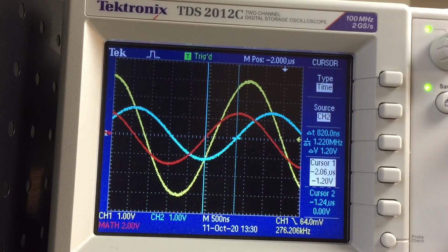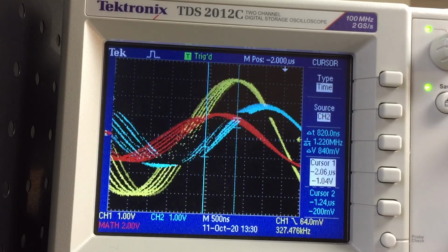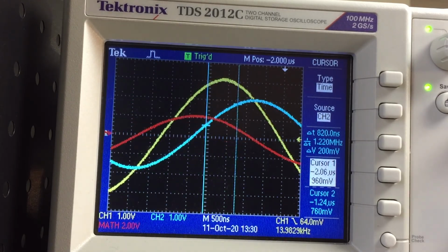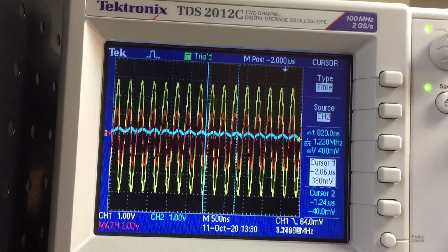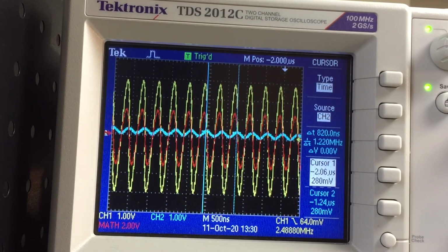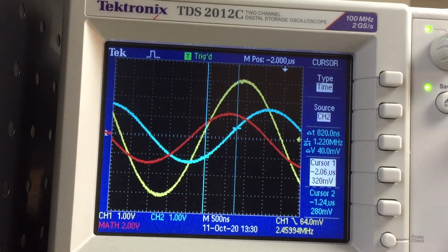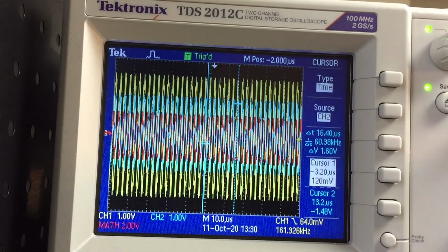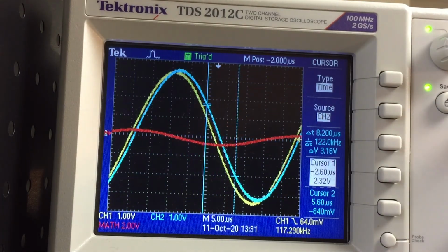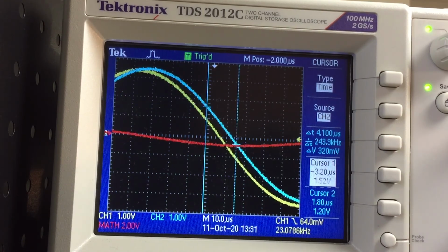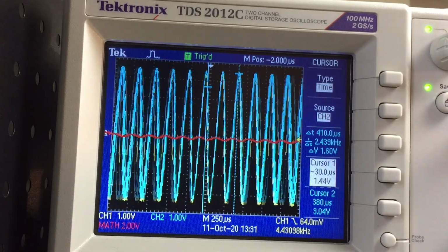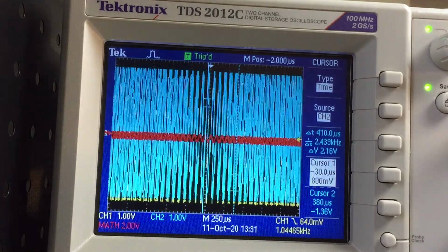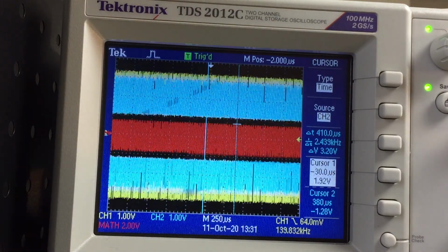Now the impedance of a capacitor should decrease with increasing frequency, so we should get more current. And let's crank it up a bit. We're pushing the limits of this breadboard, but let's do it. Indeed we do get more current. Let's crank it down now the other way. And we're going to have to scale out on our oscilloscope here. Where's that red trace? And we're going to crank down the frequency, and indeed we get a smaller and smaller current for lower frequency because the impedance is increasing. More effective resistance, frequency-dependent resistance, means less current.